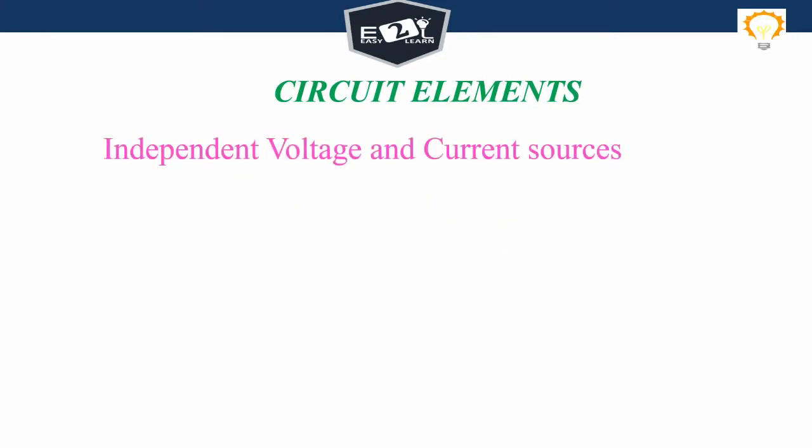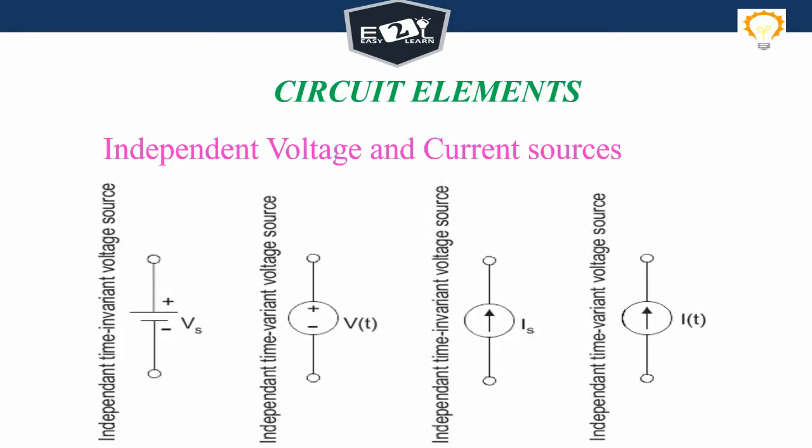An independent voltage source maintains a specified voltage across its terminals. The voltage supplied by the source can be time-varying or constant. An ideal independent current source maintains a specified current. The current provided on the circuit symbol is maintained regardless of the voltage difference across the terminals. Even the voltage polarity is unknown and must be determined from an analysis of the overall circuit. There is no need to assume a current direction. The current supplied by the source can be time-varying or constant.